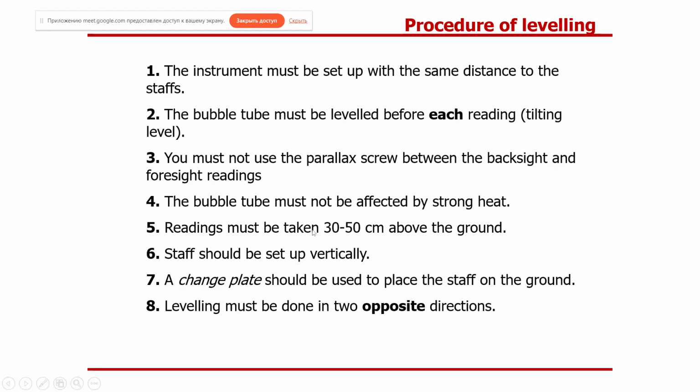Readings must be taken 30-50 centimeters above the ground. You probably remember that it helps us to avoid errors caused by refraction.